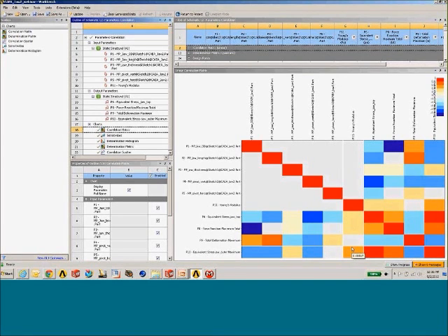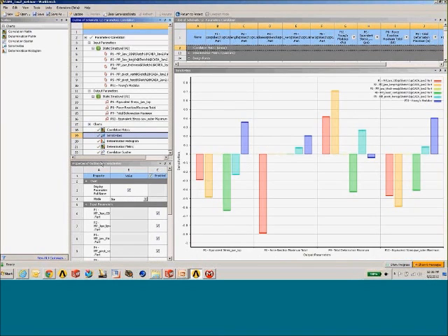So I think just by looking at this, we can eliminate from our DOE parameters 3 and 5 just based on their weak correlation to the response. We can further evaluate or confirm that by looking at the global sensitivities of these parameters. If we go from output quantity to output quantity, displayed across the bottom here, we can see that there is virtually no response for parameter 3 for the various outputs. So that one we're going to eliminate right off the bat. Looking at parameter 5, it has the weakest response of all the different parameters, with the exception of parameter 3. But the remaining ones, parameter 1, parameter 2, 4, and then P11, the Young's modulus, have a fairly strong coupled response with the output. So those are parameters that we're going to hang on to.